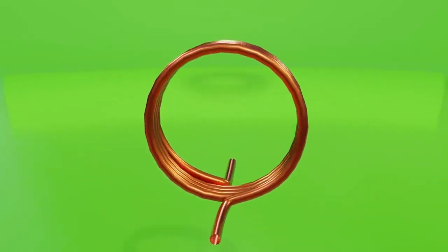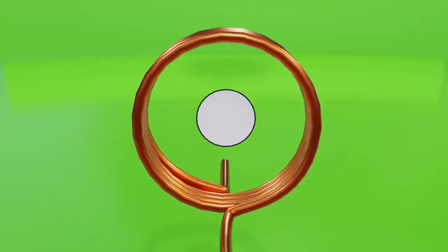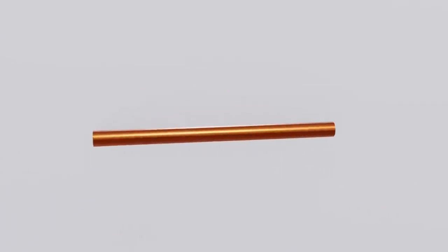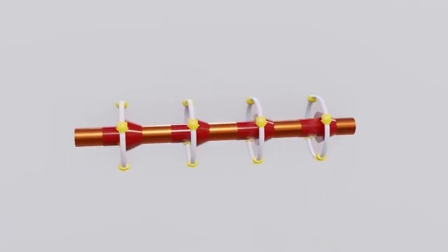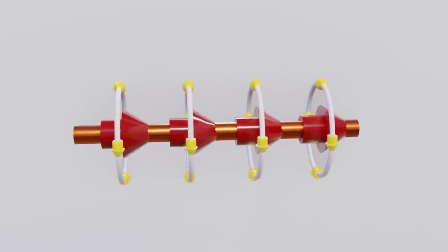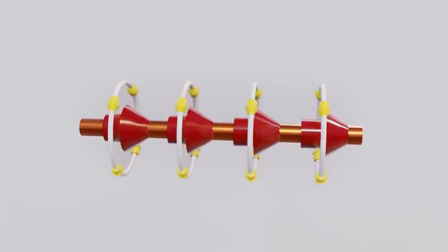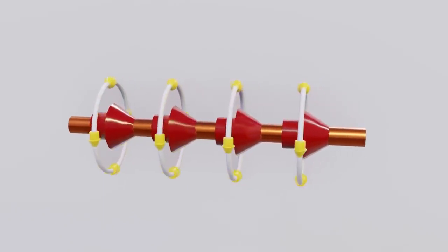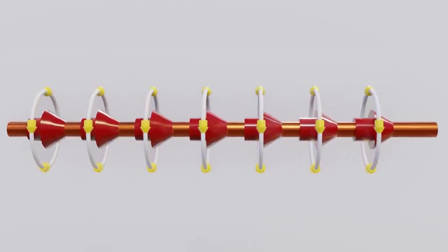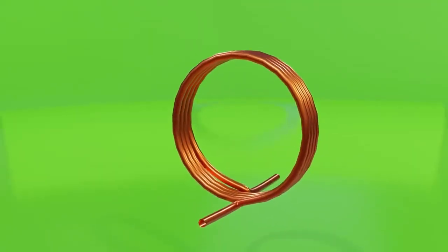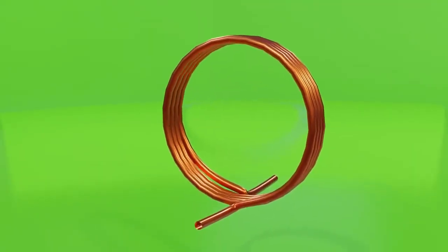The third and fourth parameters are directly related. They are the area and perimeter of each turn of the wire. One way to understand their effect is to think about the distance the current must travel to finish each turn. Although a constant current in a segment of wire will always generate a magnetic field of the same intensity, if we lengthen that segment, so will the magnetic field. In other words, the larger the loop, the greater the inductance.